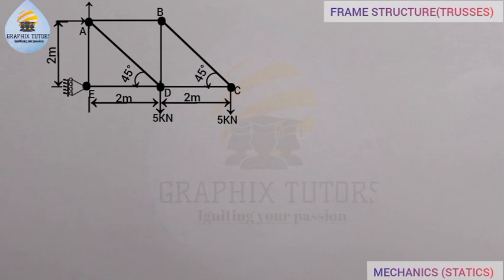It can only go in the vertical plane, upward and downward. So you allow the arrow to point in the direction that it is not moving to. You can either point right or point left, depending on what you actually want. By the time you are done solving your question, it will tell you if your direction is correct or not, right? Similarly in the hinge support too, you cannot move in any direction. That is why I'm taking two, X and Y, right? Either it is facing up or facing down, or either it is facing left or facing right. Once you are wrong with the direction you've taken, at the end of your solution, you see that the direction you took is not the right direction. So this is what we have as our free body diagram, right?